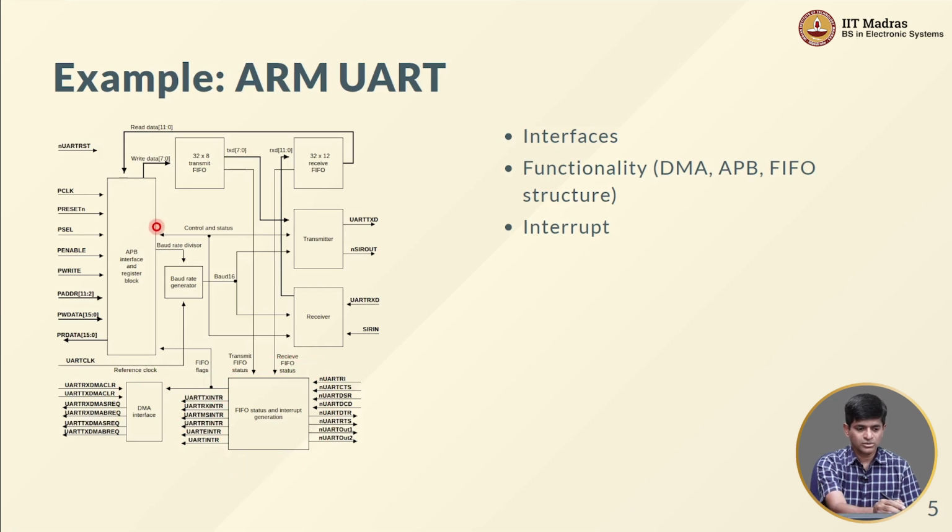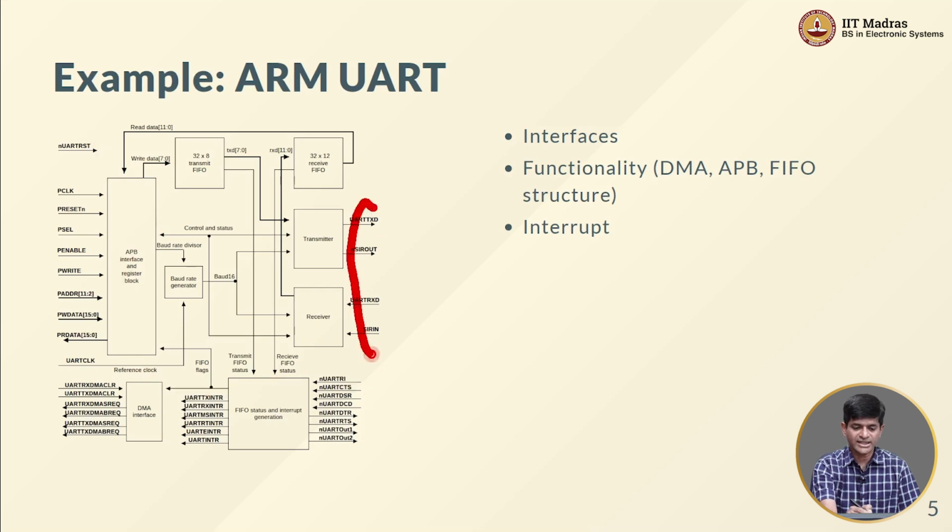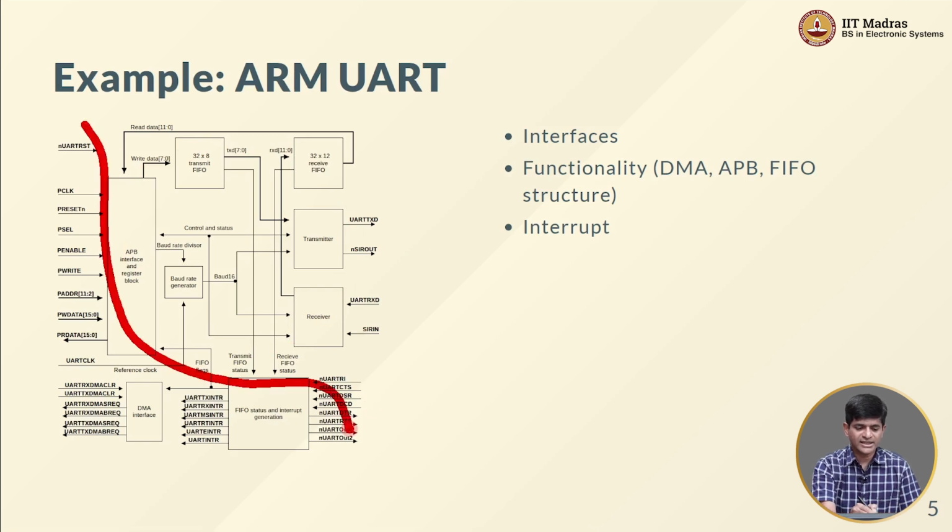So, if you look carefully, you will notice that the number of interface signals that are related to the control and management of the UART is much higher than the actual signals that are required for the UART to operate, okay, which is not uncommon. You could typically have quite a few devices where perhaps this entire module that you are creating may not even have some kind of communication with the outside world. It might just be some computation that is performing internally, but the rest of the interface that it needs in order to communicate with the CPU could by itself start to get a little complicated.